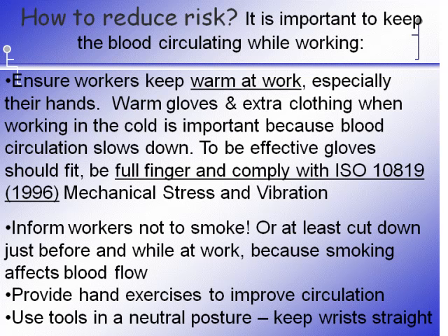If you're going to buy a vibration dampening glove, make sure it's compliant with the ISO standard. And as a professional ergonomist, I'm somewhat against them because research hasn't really shown that they decrease the exposure transmission significantly into the worker's hands. One of the reasons behind that is when you're wearing a vibration dampening glove, it's got a big pad in it like an innersole. You're putting that between the tool and your hand, and so now you're functionally making your hand smaller, and some workers have to grip that much harder.